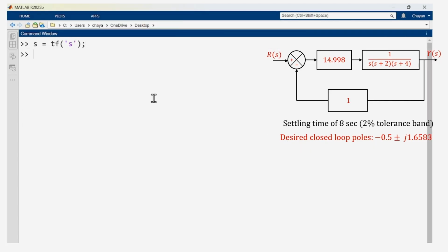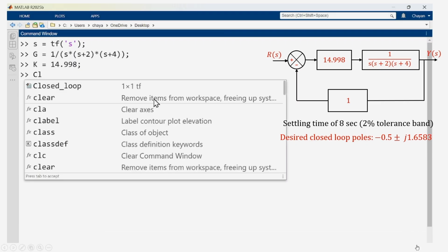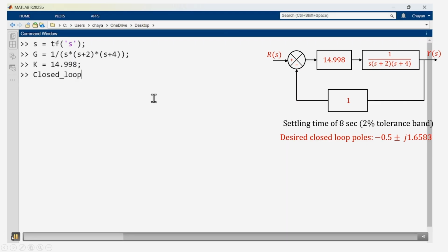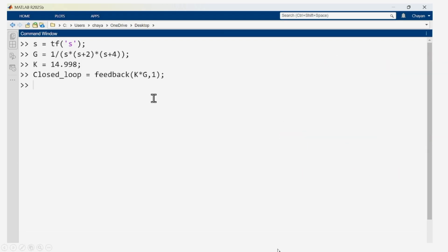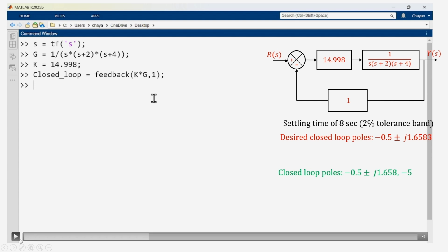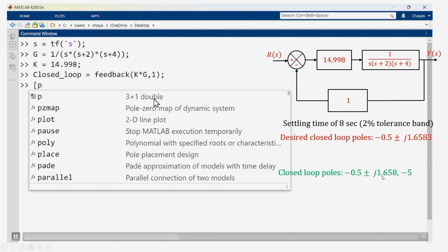So, now let us look at MATLAB and see whether this works or not. I am doing the same steps that I did for the previous examples. So, up to this I have found out the closed loop pole locations. Again, k was this. So, I have correctly found that, and see the desired pole location in this case is this. Okay. This was the desired pole location, and if you go ahead and find out the closed loop poles, they will come out to be these.